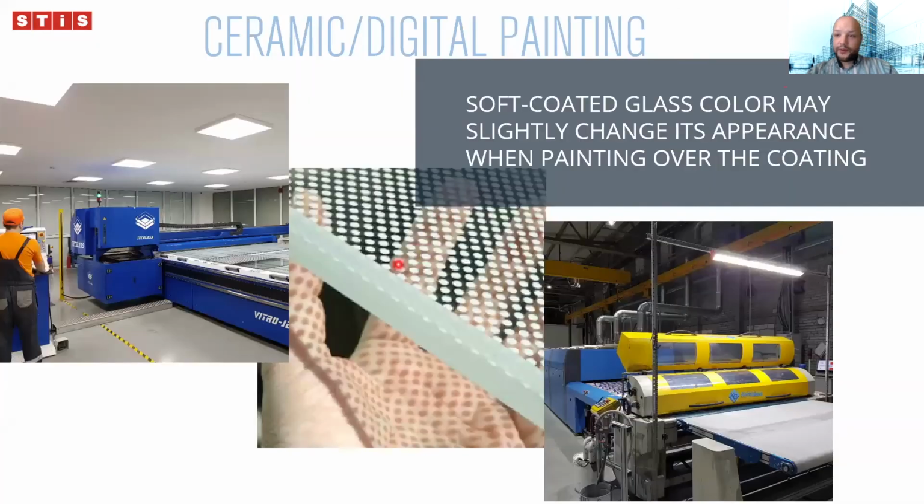Now let's talk a little bit about ceramic painting or ceramic print. Soft coated glass can be printed, can be painted, but here you may again have several problems on the tempering side. Simply because if you paint half a glass with the paint and leave half of the glass with the coating on it, that means half of the glass has low E properties, while the other half does not.